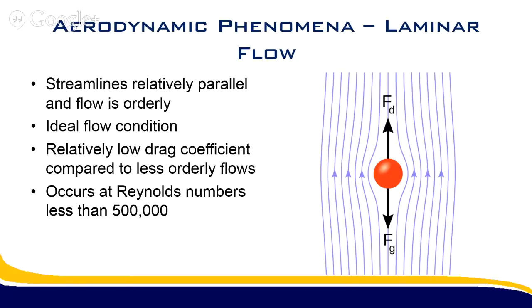So if that's any reference, of course, I mentioned there was a reference length. Commercial aircraft are also really big. So it's kind of a trade-off, but it basically compares the inertial forces to the viscous forces on an object, and its ratio. So 500,000 actually for aerospace applications is a really low Reynolds number.